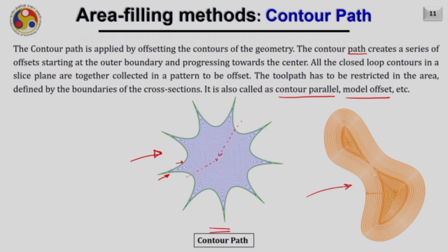The one here you are seeing is another example of a contour parallel toolpath, and the thing I want to highlight here is some advantages and disadvantages of this tool path. The feed rate will remain quite consistent while depositing on these tool paths. However, one can notice that some voids will remain while deposited by these tool paths. However, if we use a combination of this tool path with zigzag, then we may get some better results.